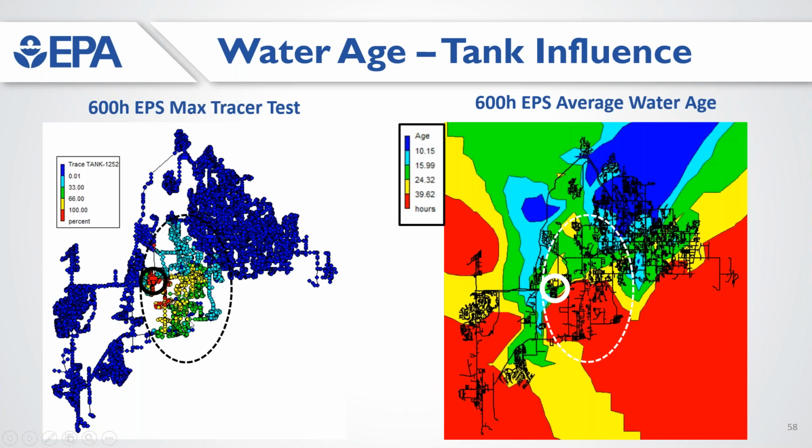And we do the trace. Yeah, he did this. We pick a tank. If a node receives lots of water from the tank here, water quality is kind of bad. So usually tank water is old. So tank operation is very important, to make sure the turnover rate is high enough to prevent water age from going up, you know.